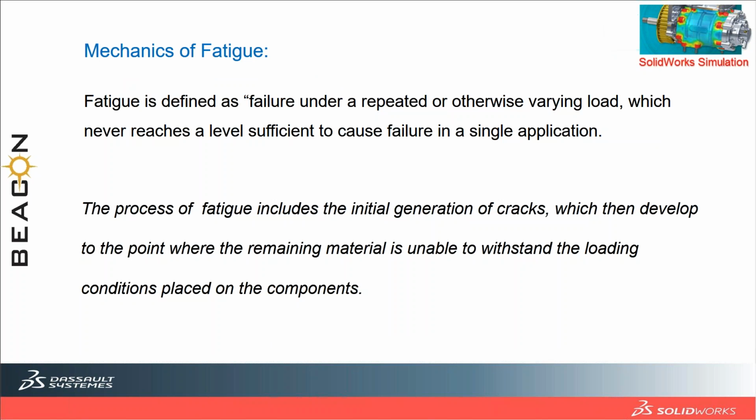Let us see what fatigue is, and how you define it. Fatigue is defined as a failure under a repetitive, or varying, load which never reaches a level sufficient to cause failure in a single application. What does it mean? Your component may not fail in a single cycle, but with repeated or continuous loading, it may fail after a number of cycles.